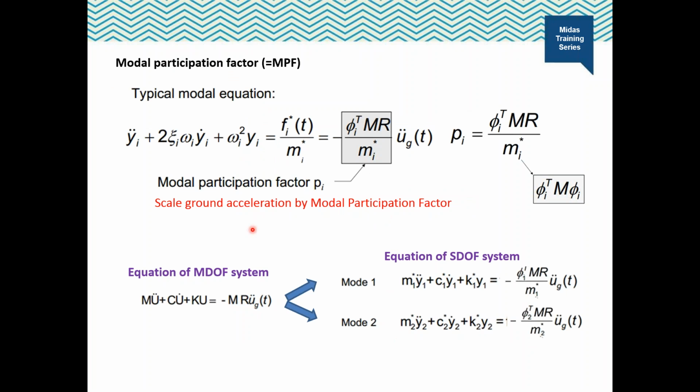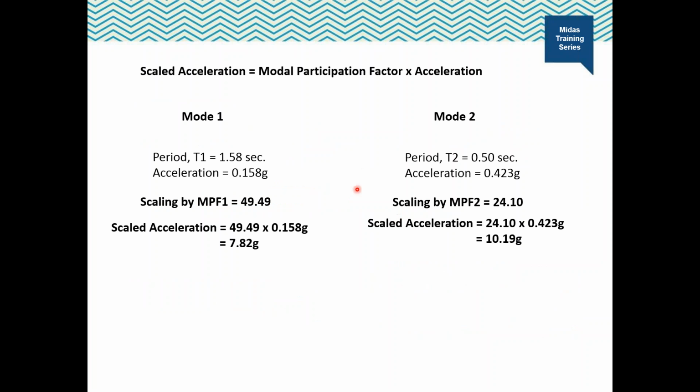If the ground acceleration is scaled, the relative acceleration also becomes scaled by the same factor. So, the acceleration from response spectrum should be scaled by modal participation factors. Then, the scaled acceleration for mode 1 and mode 2 are determined like this.